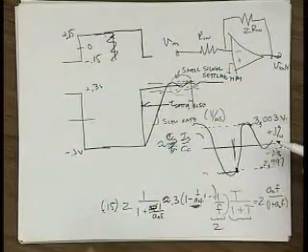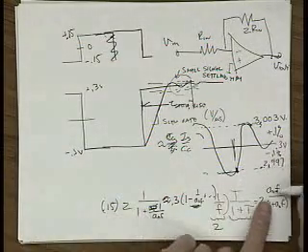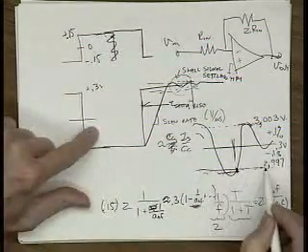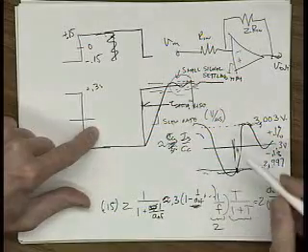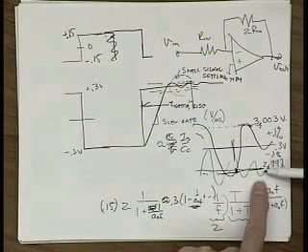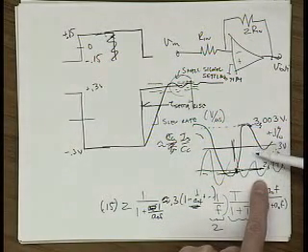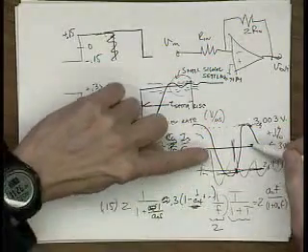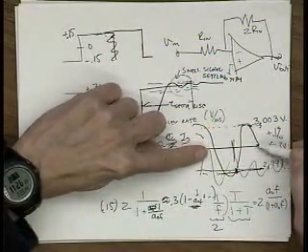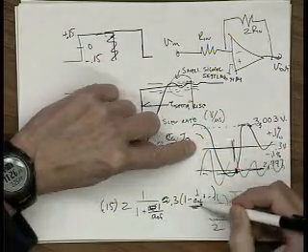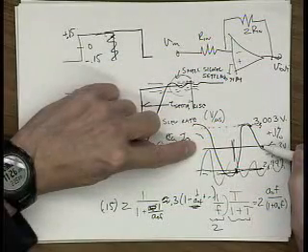Now, clearly, if you made your gain as small as possible, so that it finally settles out to this 0.2997 value, you can see what's going to happen. This thing is going to keep wiggling, and it's going to keep coming out of the error region that you allow for settling, until way, way out here. Maybe forever. So there's an advantage to having the static settling error, from A0F, be fairly small.